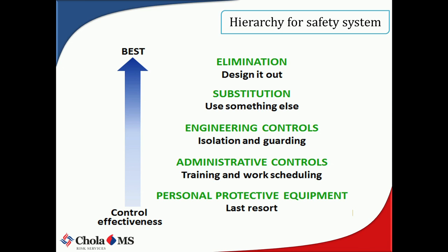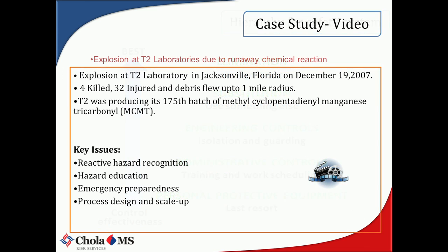Okay. So, whatever you do in your life with respect to safety tomorrow, this will remain the fundamental. Anything that you work on in safety engineering is based on this. Not only safety engineering related to process, it also relates to your occupational safety. You talk about machine guarding, exposure to noise, exposure to dust, whatever, everything follows this same thing. Now, why I want to touch upon this point is, when you do a hazard analysis and when you talk about arriving at a risk control, this is the hierarchy which generally anybody follows when you are trying to come out with a control.